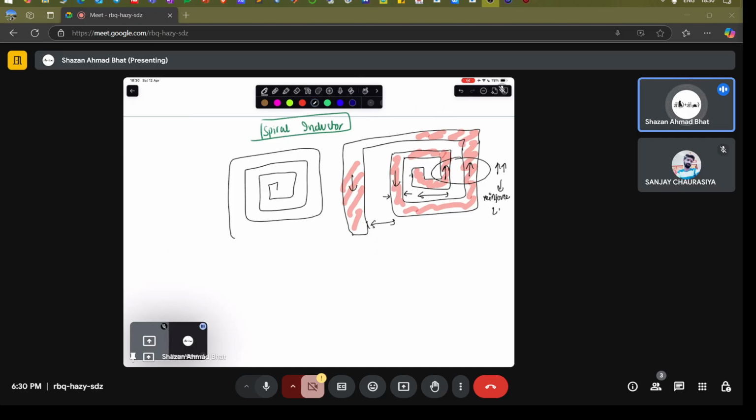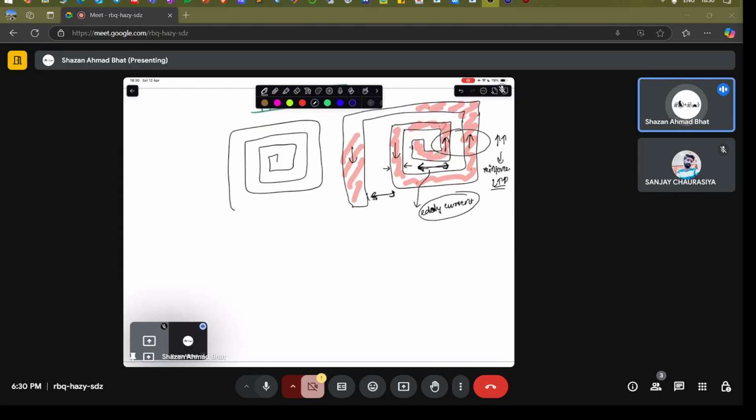It will increase the inductance a little bit. It's going to affect the inductance. Everything is going to matter, and these dimensions, which are these particular double-headed arrows, are going to determine how the losses will take place, because there will be eddy currents also flowing in this system. Because you have made a loop of these currents, the eddy currents are going to oppose the original currents.